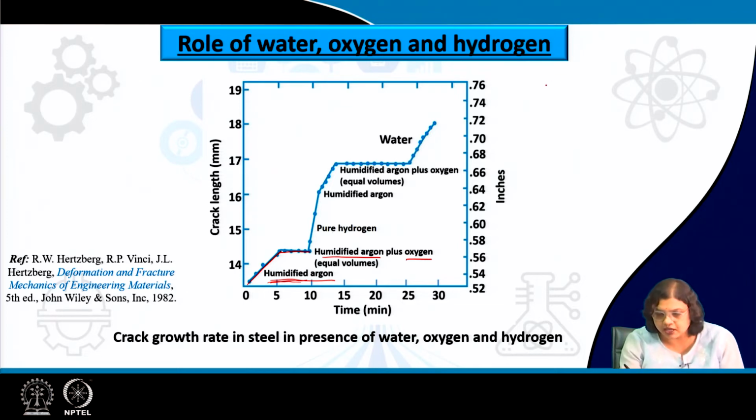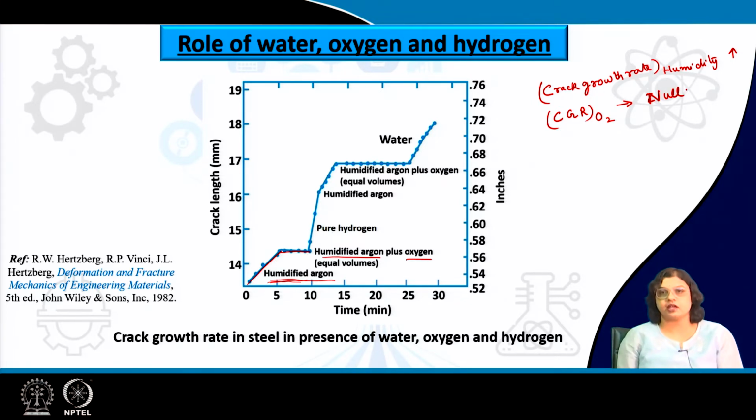Now, that is very interesting. While in one case we are seeing the crack growth rate in presence of humidity is quite high, the crack growth rate in presence of oxygen is actually 0. So, the crack is getting completely arrested in presence of oxygen.